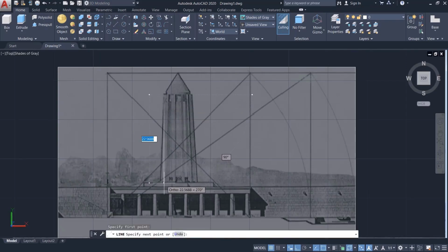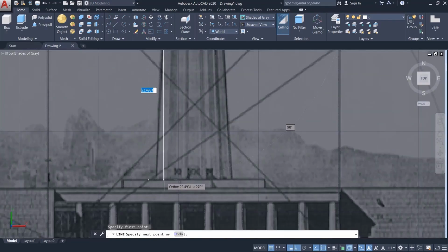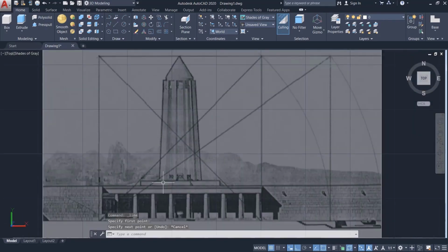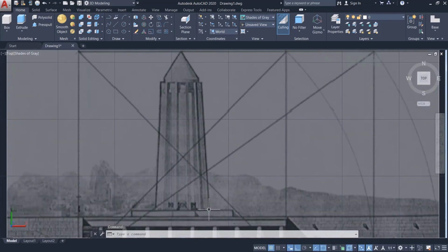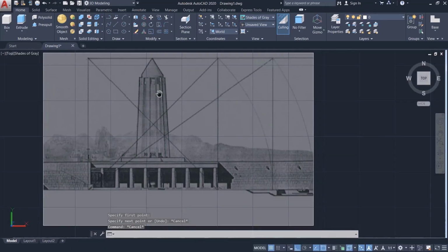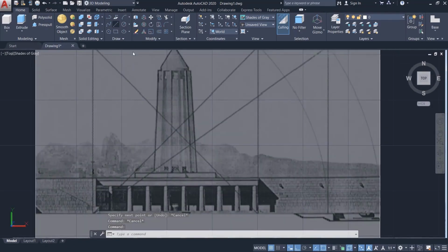From here to here is about 23 meters. Yes, so why did we do this? So that we can have the correct height ratio. We can read the width ratio from here, because we don't know the size of this tower's cross-section. When we don't have any dimensions or measurements, we can use this method, because for many of these, the plan might not even exist. Alright, we need to make the image a bit bigger so it lines up properly. Let's make this 23 precise too, so we don't have to worry about it anymore.